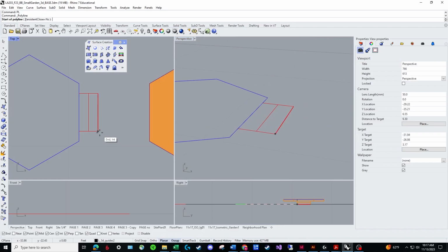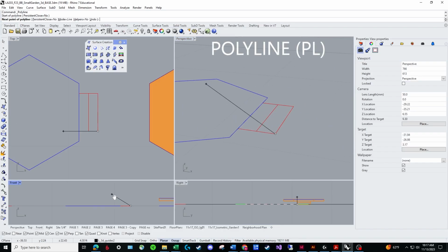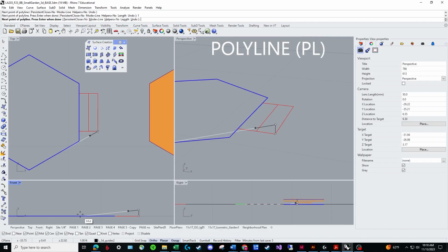And we'll start with just drawing, let me get myself into position here. Start by drawing the profile of the section of the stair. So 0.5, and I go ahead and left click, and the way I'm doing this is actually typing in the length 1, and then you can see the white line is saying this is the direction we want. Well, I'm going to ortho this so that it stays in orthographic projection, 90 degrees. I must also be careful, look at what this is doing. It wants to O-snap to all this different stuff. So if this starts happening and you can't control it, just turn off your O-snap.